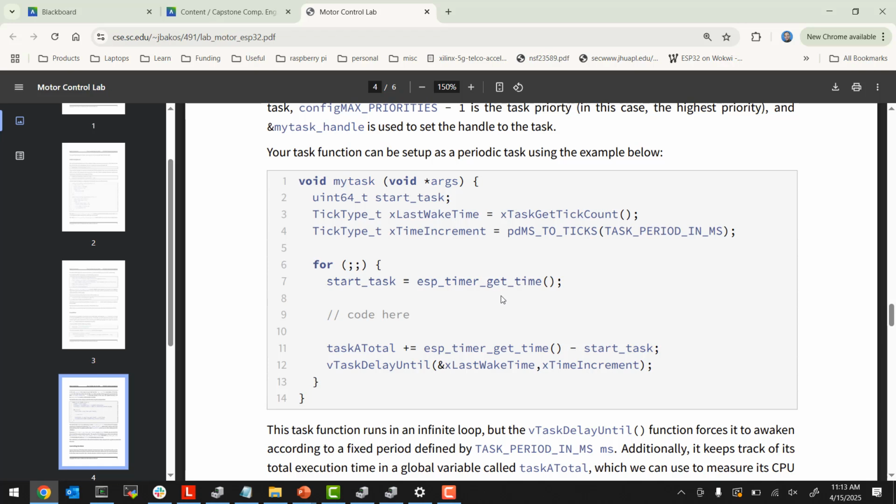Now, here's the issue with this: FreeRTOS doesn't have a schedulability test. So how do you even know if your tasks are requiring more than 100% utilization of the CPU? Now you might say, well, there's 2 CPUs. No problem. No, only one's used. It's effectively 1 CPU. So you can't exceed 100% utilization. So how do you know what your utilization is?